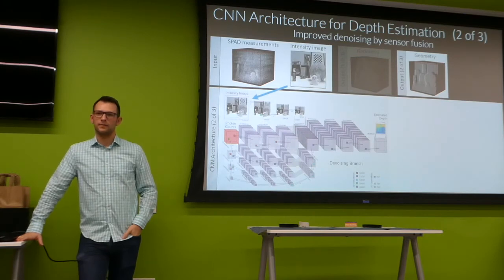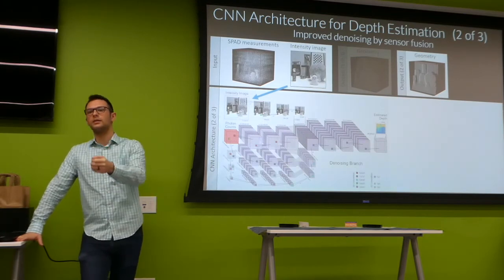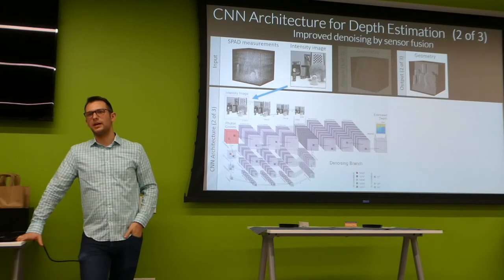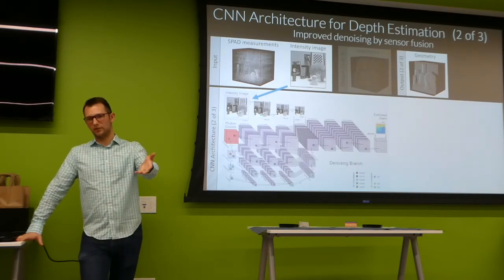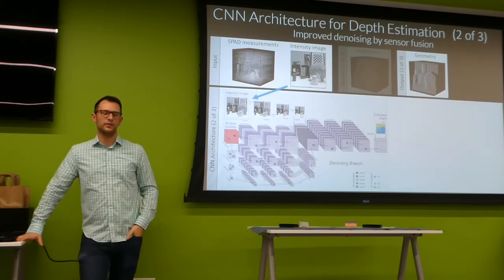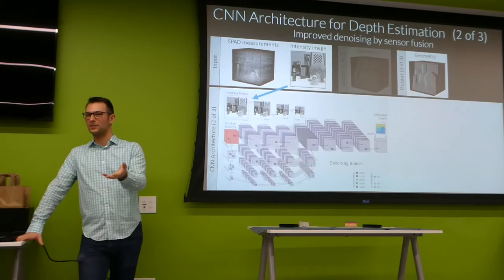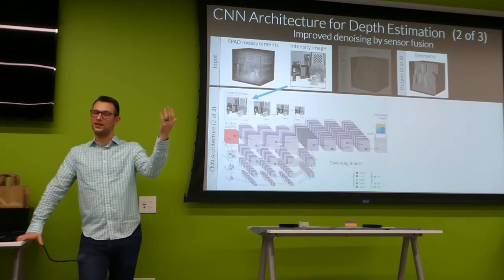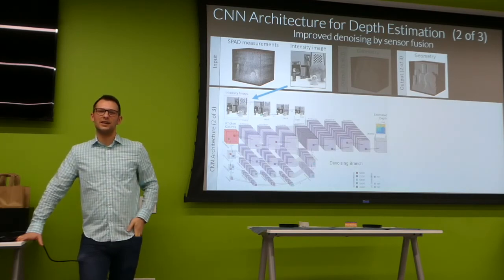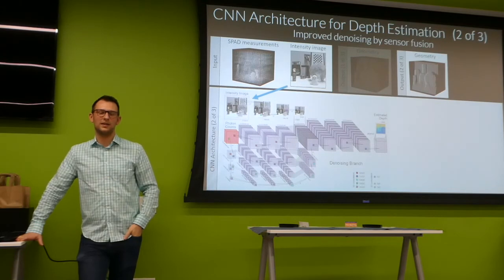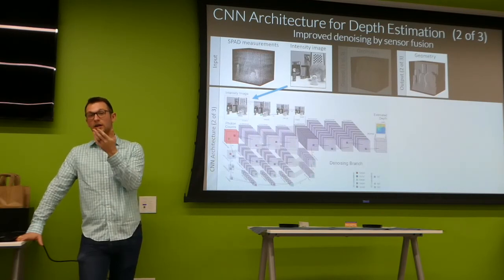No, it's fusion. There is radar too. It's a fusion of sensors. There is no LIDAR, but there are other sensors, not just cameras: cameras, radar, and ultrasonics as well. Right, that's true. There are challenges with using stereo cameras. Maybe the radar helps alleviate this. If you have a textureless region where you can't tell what it is, it's going to be pretty hard to estimate depth there just using stereo matching. Maybe the radar helps with this. LIDAR would help you get to better depth resolution.